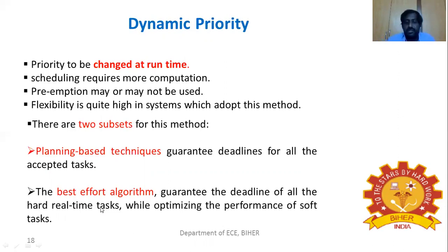And the best effort system guarantees the deadline of all the hard real time tasks, because a hard real time task should be finished within the deadline. Otherwise, many failures or lifetime related issues arise. Best effort systems guarantee the deadline of hard real time tasks while optimizing the performance of soft tasks.